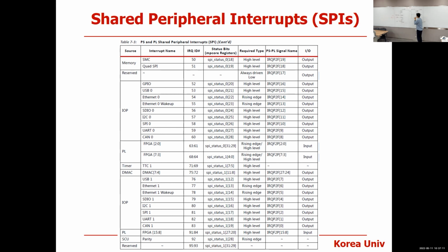Okay. And then let's say the private timer is generating an interrupt, or your custom logic is generating an interrupt. Then what do you want to do? The interrupt will be delivered through the distributor and CPU interface, and eventually go to CPU 0. CPU 0 will be interrupted in the middle of executing some program, let's say a hello world program.